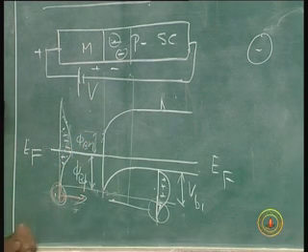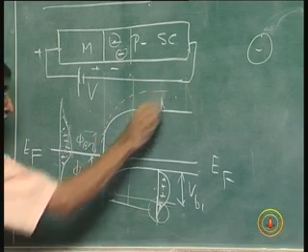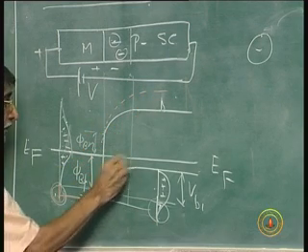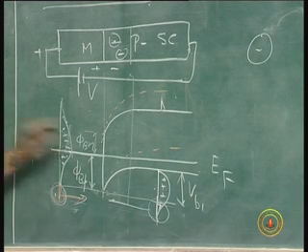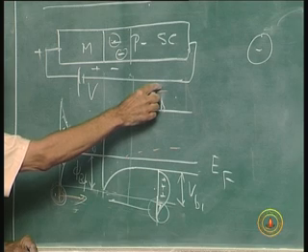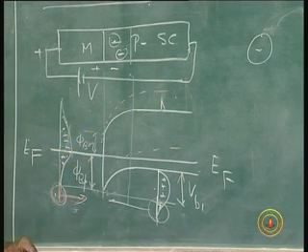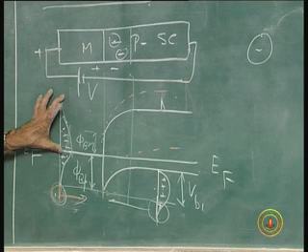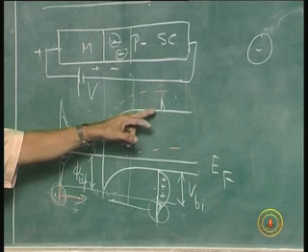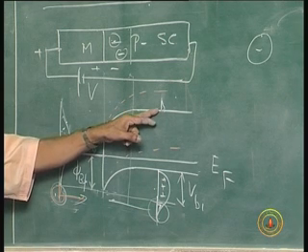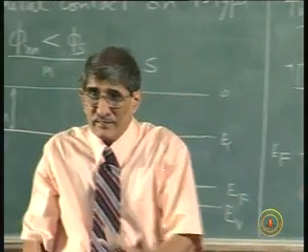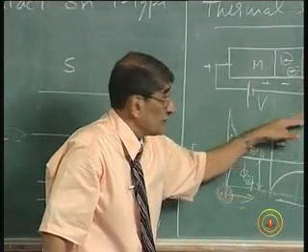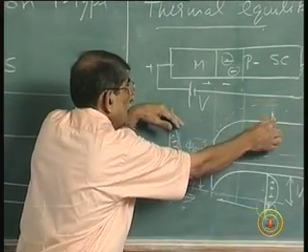This whole thing will go up. This will actually go up like this, okay, and this will go up like that. Okay. So, you have the energy band diagram gone up. When it goes up, this will go up there, this will go up there, that is the minority carrier, and this actually is not changing. So, current due to electrons will be there, a small current because of this minority carrier, okay, which will be very, very small, like the p-n junction minority carrier current, that will be there rolling down, because you have taken it up and this distribution goes up here.